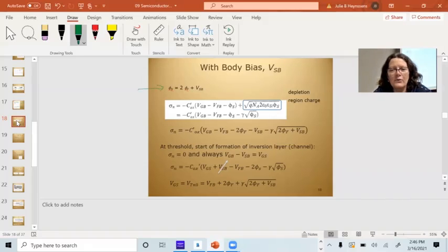Okay. So in order to overcome the energy at the barrier, so that I can create the inversion layer, the minimum amount of energy I need is 2 phi f minus VSB. I rearranged the slide a little bit today. We've got an expression for the total amount of charge at that barrier. We've already kind of figured that out. I'm going to take this Q term right here.